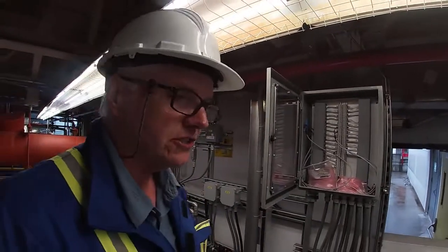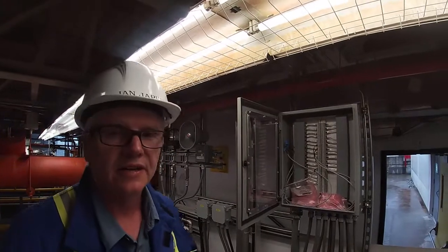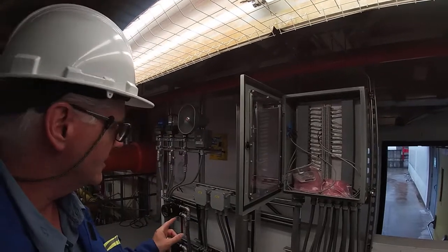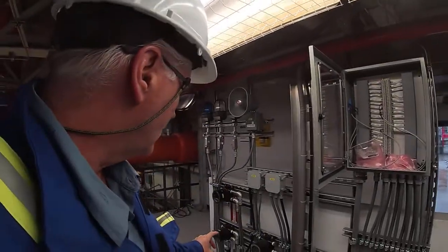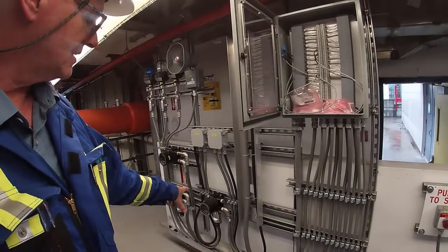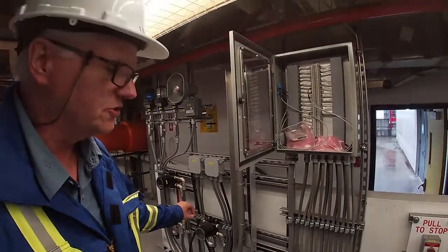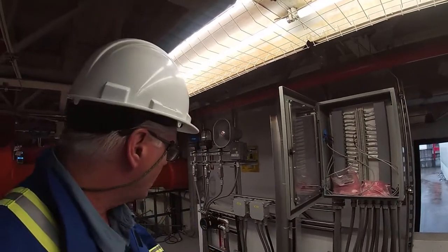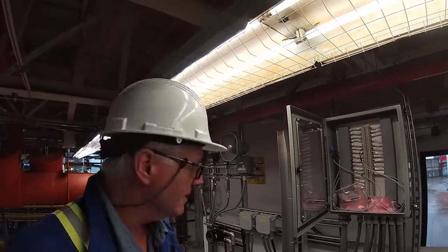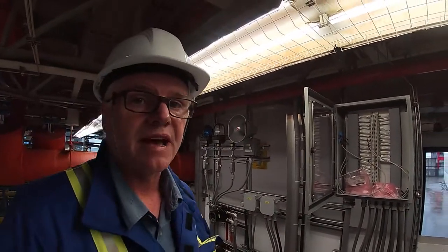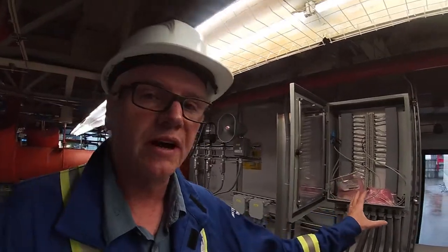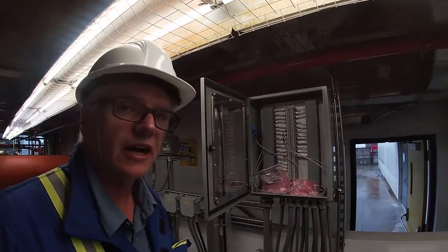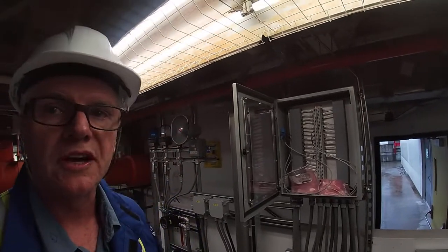And we'll do a calibration, then some tests on it, and make sure that we check out the SIS system. One last thing is that normally you would want to do the calibrations with a magnet, and that's what we'll do. The reason being is if it's in a classified area, you don't want to open up a device that could be arcing and sparking. Therefore, it's better to use a magnet. But if the junction box, for example, was in a non-classified area, by all means you can hook up here and use your communicator to do the calibration.